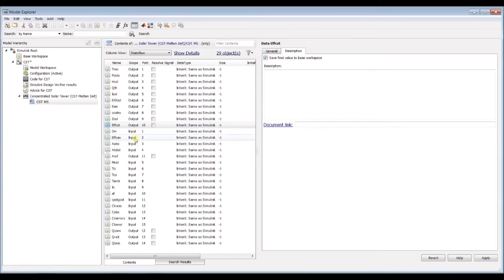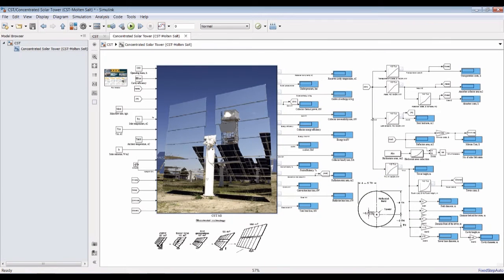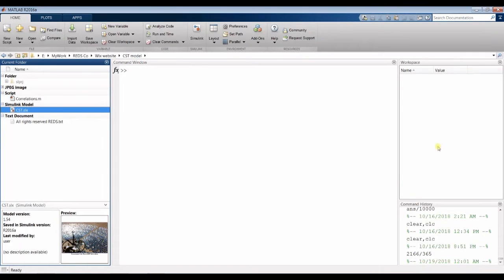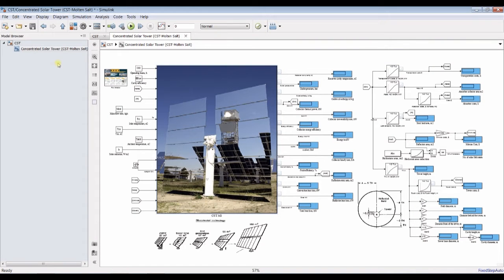You can add collector inlet efficiency, TCN, which means temperature collector inlet, mass flow rate in collector, total mass flow rate, ambient temperature, and solar radiation. Don't forget to hit apply. By checking this, you will be able to collect data or matrices or whatever from here, or export it to Excel sheets. It's quite interesting.